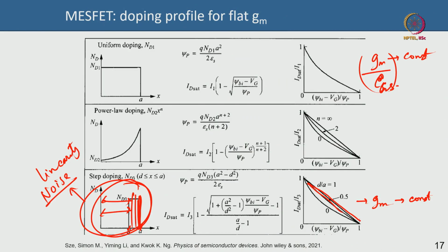In the last lecture we basically ended at different kinds of grading profiles for engineering the transconductance profile, and what kind of transconductance profile gives you better linearity. It is a flat kind of a GM. If your GM stays flat, that means it is a linear gain, and that helps you in achieving linearity at the system level. And to get a flat GM, people have found that you can change the doping level in the MESFET, especially if your doping is higher far away from the gate, then that actually helps. That is all fine with the physics, we talked about saturation, the drain pinch off, and the IV relation, etc.